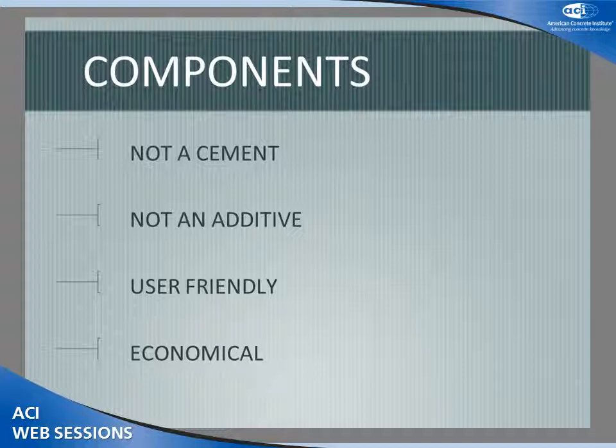Now, the Type G advocates will tell you that their system is better because it expands lockstep with the hardening of the concrete. And the Type K people will tell you that their system is better because the final expansion is achieved after the concrete has hardened. This is one thing that we can pass on. This friendly debate could be considered moot, even irrelevant, since the difference in the cure rates is taken into account when using the member expansion graphs in 223 during the concrete mix design formulation.